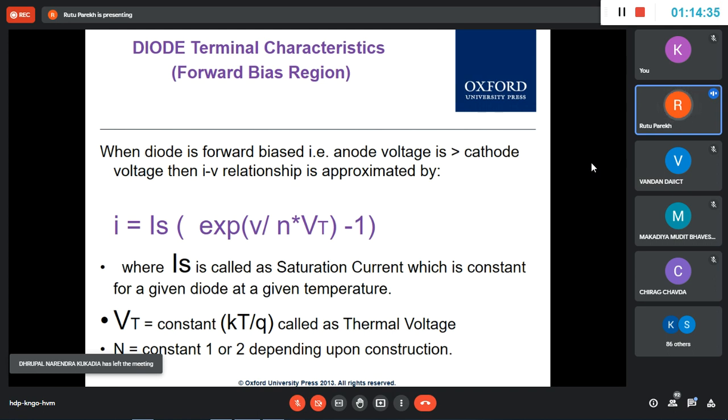When you are sensing, a sensor is to sense some environmental or biological parameter. The electronics here is R, V, I or capacitor. Because of the external factor, like pressure or temperature, R or C or something will change, and we have to measure this. It is easy to measure R instead of VT. Your point is correct. If you get into more physics of that, you can find out VT also. But we convert, say, temperature to R. So the temperature sensor, with the change in outside temperature, the R will change.